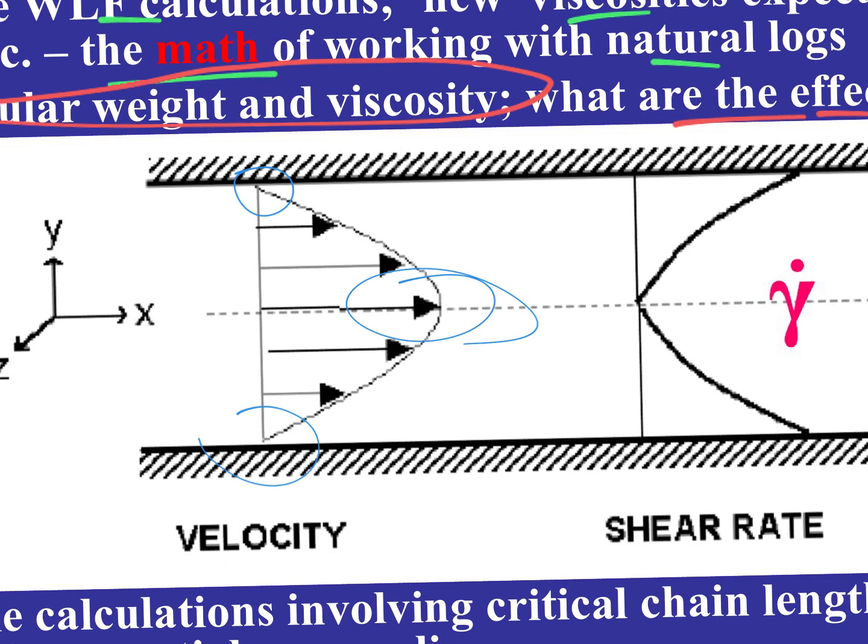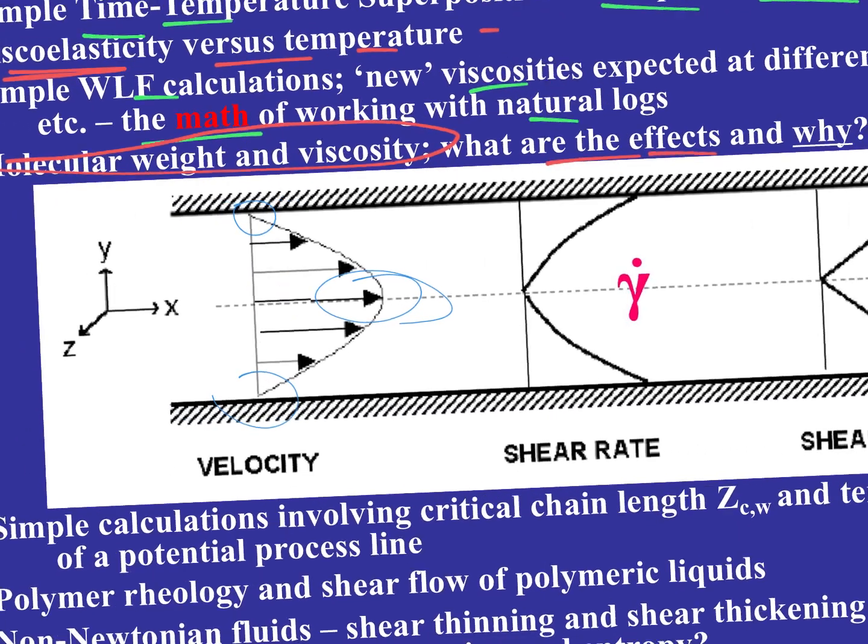All right, so we're all familiar with that. What's the velocity at the wall? 0. Okay. So start from there and look at this concept as a series of different layers being sheared relative to each other. And obviously that must be a pretty substantial amount of shear because this one is going down there and making a part. This one's not doing that. So obviously there's a ton of shear in these systems. And so that helps guide us in terms of understanding what can be molded and what can't be molded.